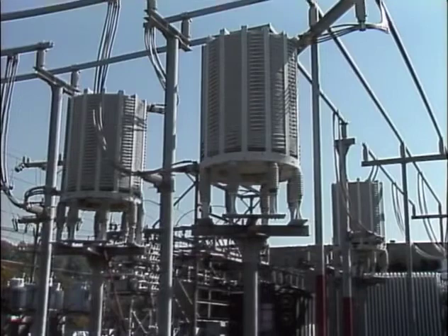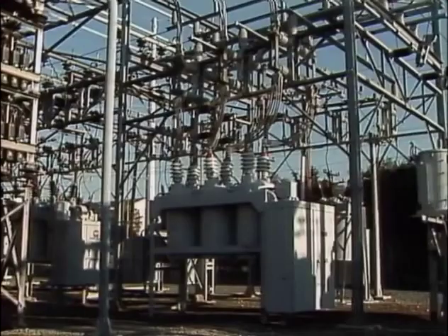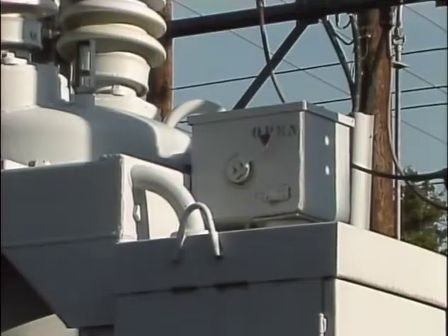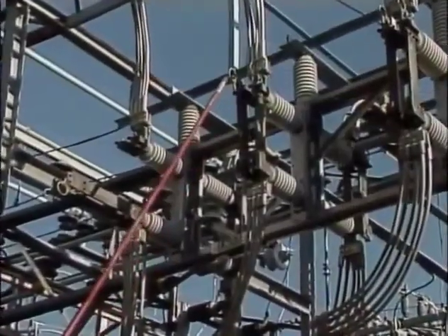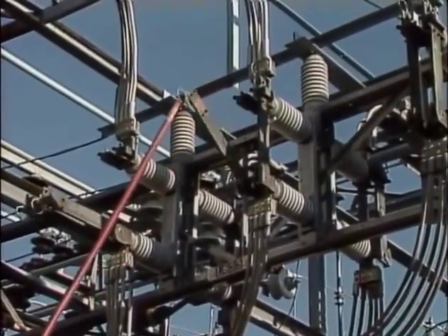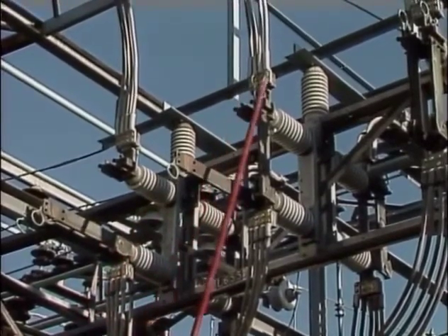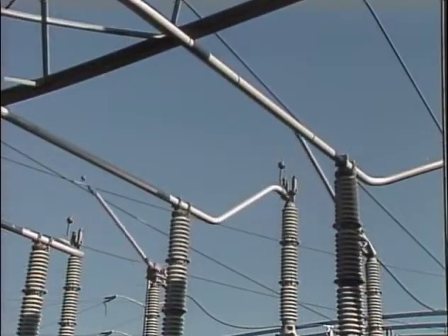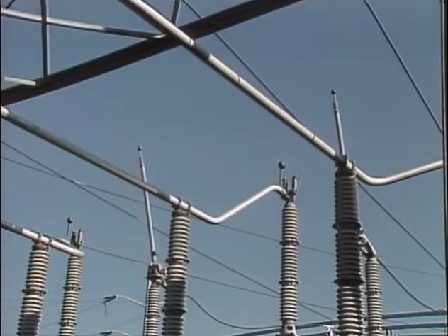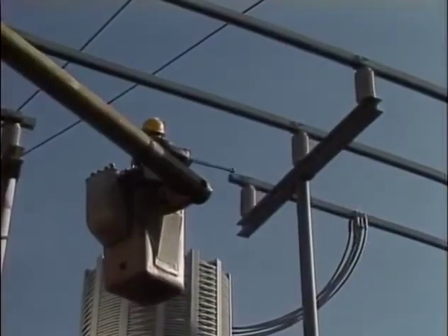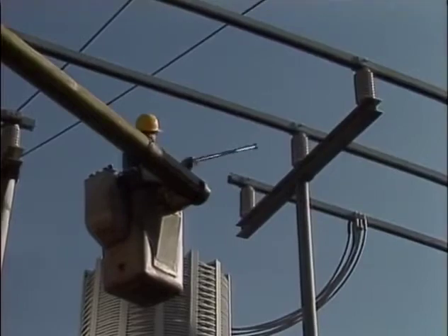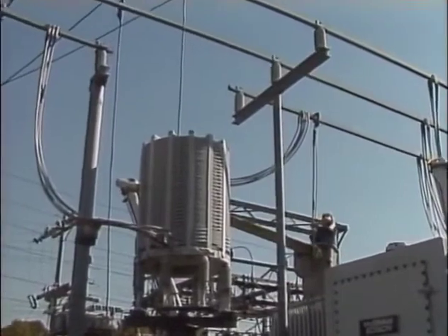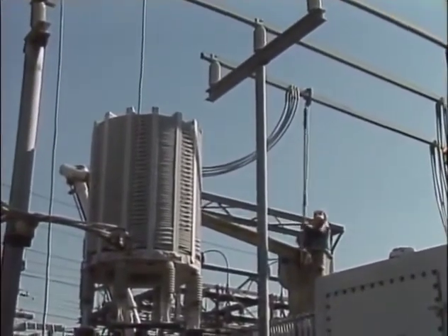To de-energize and isolate these reactors, first, a three-phase feeder breaker is opened. Opening the breaker removes the load from the circuit that the reactors are in. Then, disconnects are opened at the breaker to provide a physical break in the circuit between the reactors and the load. Finally, motor-operated switches are opened to provide a physical break in the circuit between the reactors and the source. After the reactors are safely de-energized and isolated, they're tested for dead and grounded. Be sure to follow your company's safety procedures both when testing a reactor for dead and when grounding it.